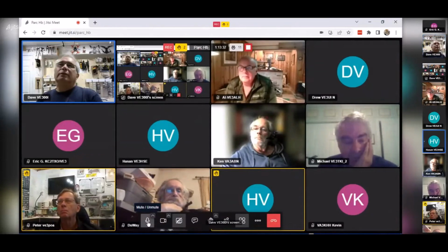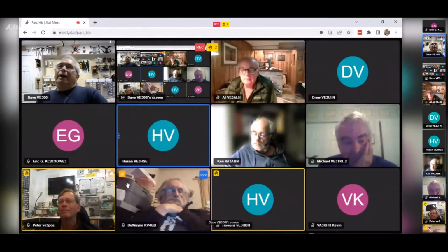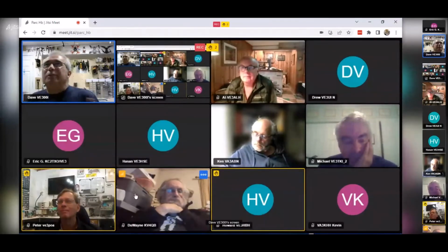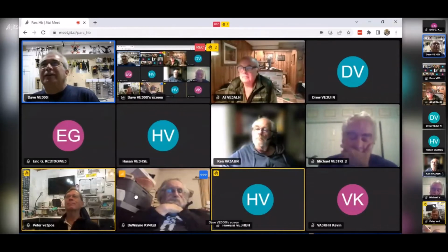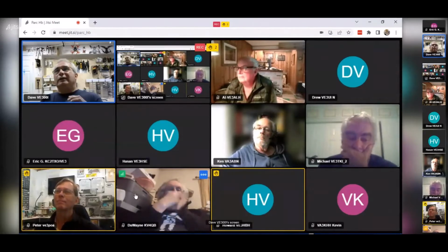Are you sure you don't just need to tune your whole system a bit more? Maybe use a higher voltage, different pulses. There's a lot of variables you could play around with. This was just me futzing around, trying to get a PID controller to work. And in hindsight, it was a terrible PID controller because it's a non-linear system.